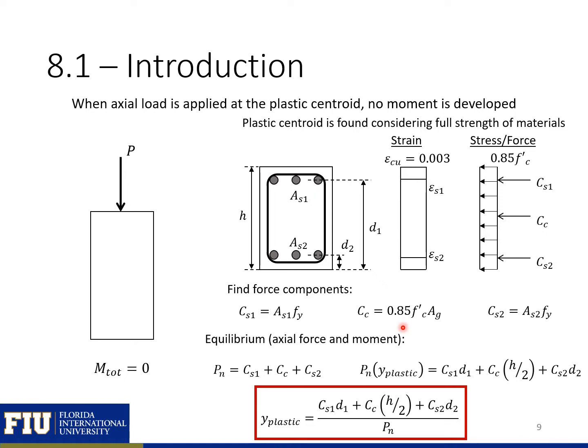points. So you can see we have our three different components because we have 2 layers of steel in our concrete section. We can take our steel out of our concrete component if we want as well. So then we can sum these and find the total force, or the total axial load capacity. And our plastic centroid, or plastic neutral axis, is just the force times the distance.